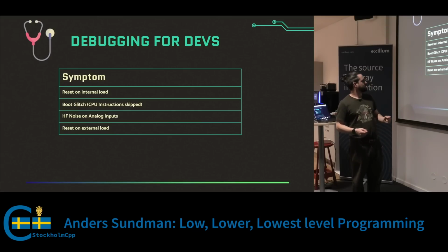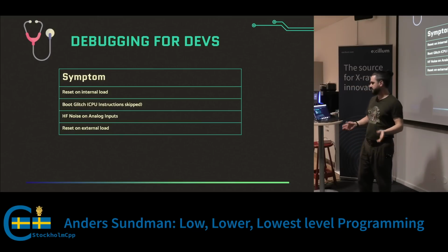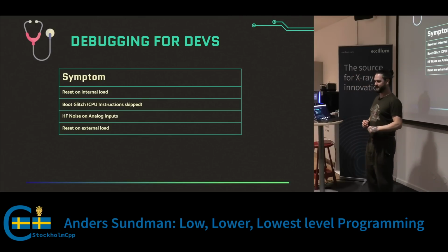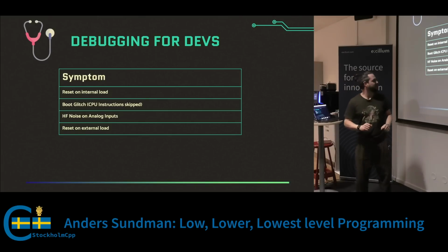If you're a hardware or security developer and you want to glitch the power when the boot is starting, to trigger some intentional weird behavior in the CPU, like skipping over a conditional branch, then you need to desolder these first. Otherwise your power toggling in the early boot sequence won't have any effect, because it will take the power from these decoupling capacitors. But then you probably already know this.